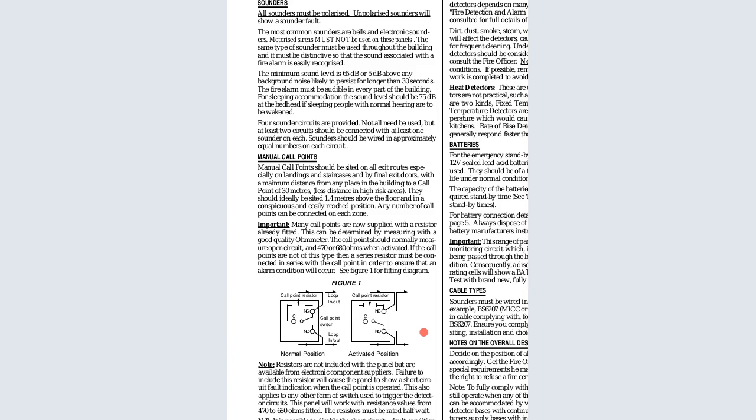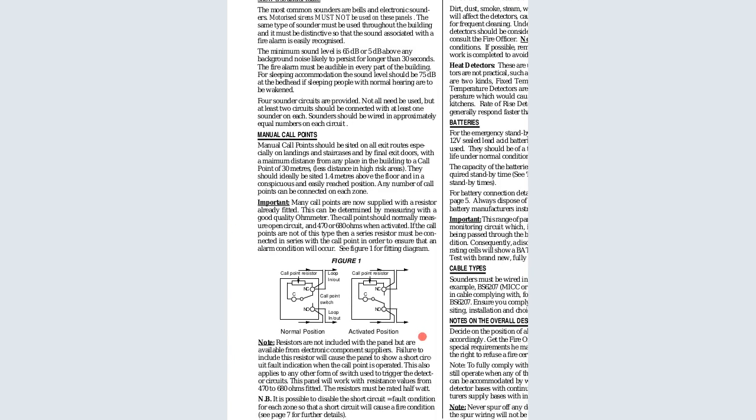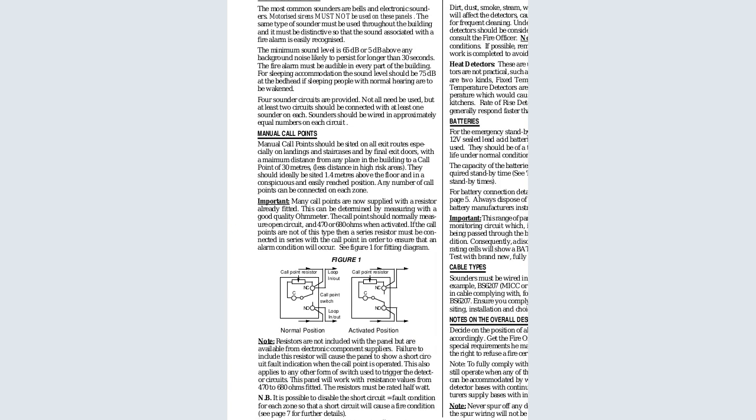The manual call points are like the switches or buttons that are normally pressed. You realize that in hallways, for example in institutions, even in schools, you will see these call points, and some of them are noted: in case of fire, break this glass. When you break the glass, it will activate the sounders to make the noise or alert people. Those are the call points. The call points are the ones that are able to initiate the process of sending a signal to the right channels.